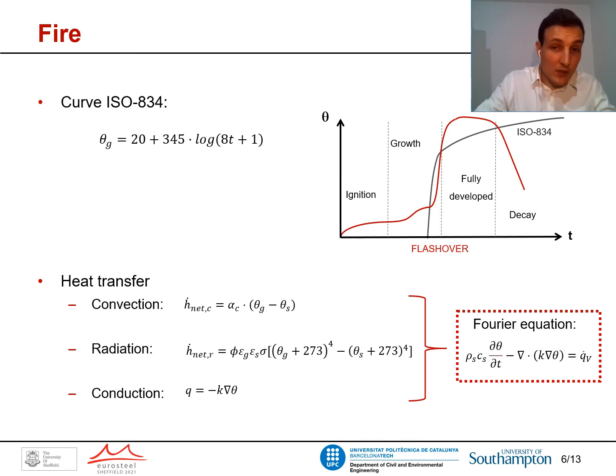Once the gas temperature is known, thanks to the standardized curve, the heat transfer between the gas and the structure can be calculated at each time step, obtaining the temperature field of the structure. When the temperature is known, the mechanical properties are updated at each time step according to this temperature field, and then the mechanical problem can be solved.